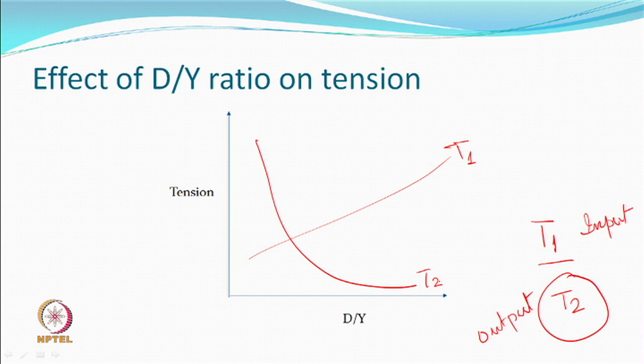When the disc is not rotating, T2 is going to be high. If the disc does not move, only yarn is moving, you can do that. You can always stop the disc rotation, and if only yarn is moving, there is only friction working. So, whatever is the tension below, the tension above could be more, right.